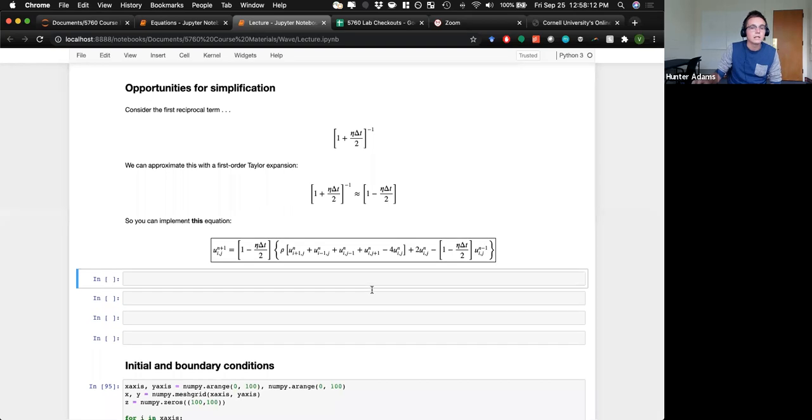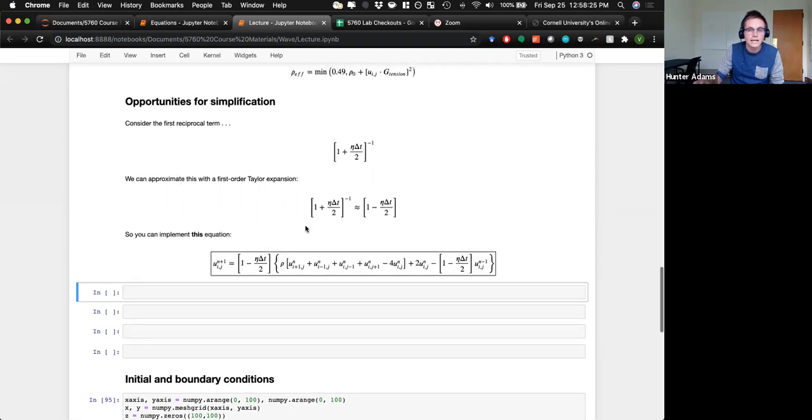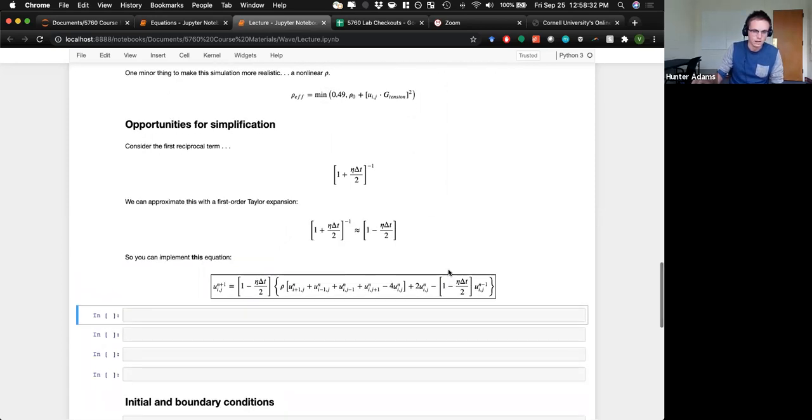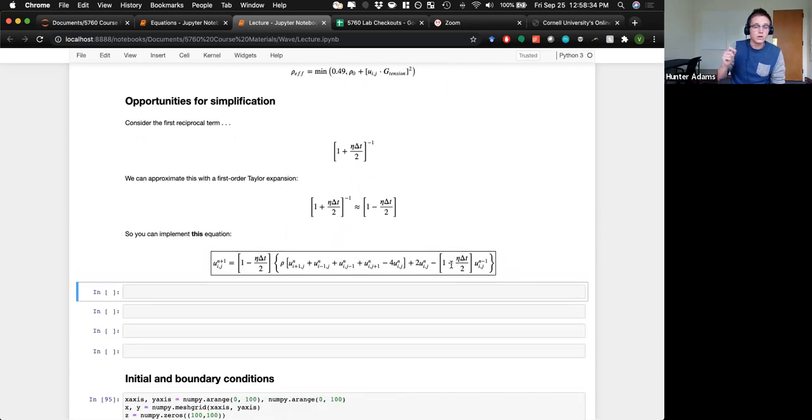So the update for each node should require, this multiplication by rho will be a no-kidding multiply. So you'll need one multiplier there, and the calculation of rho will also require a no-kidding multiply. So when you update each node, I expect that you'll only require 2 hardware multiplies per node.